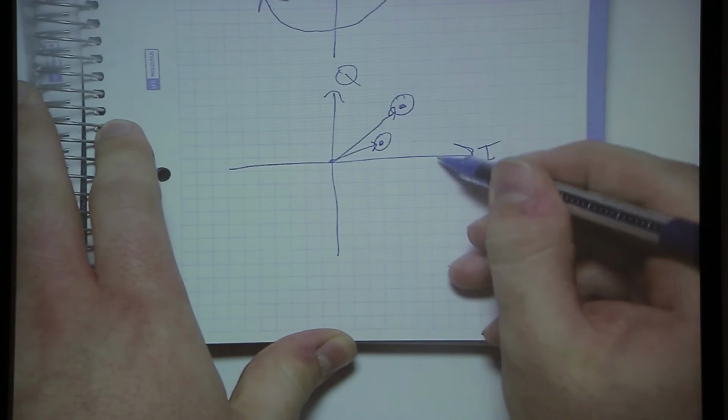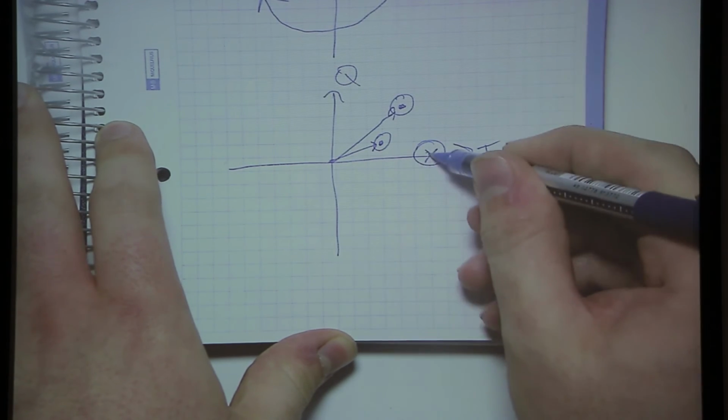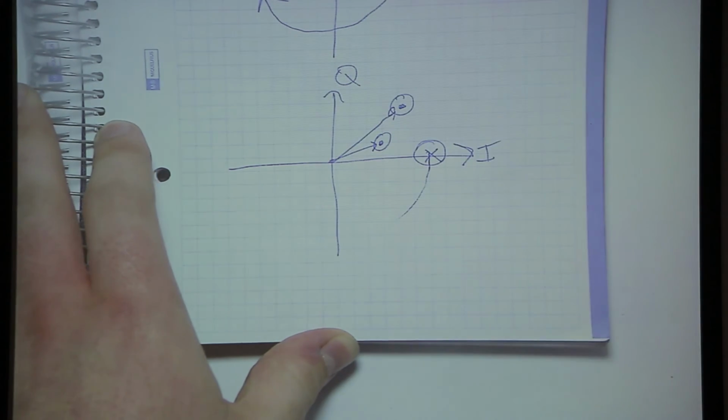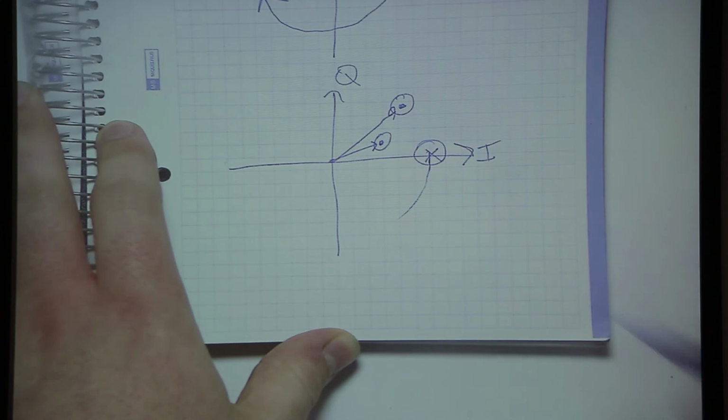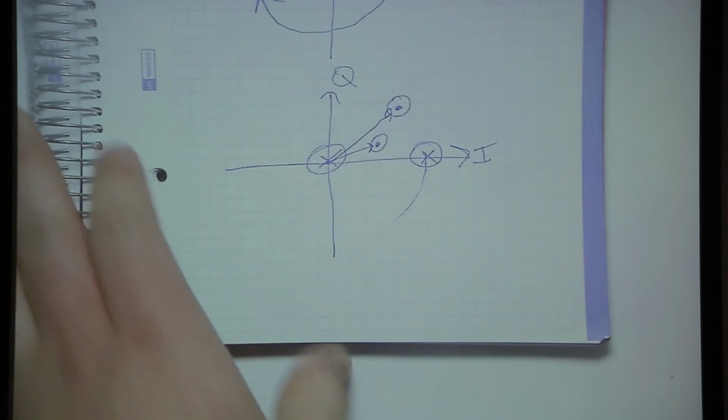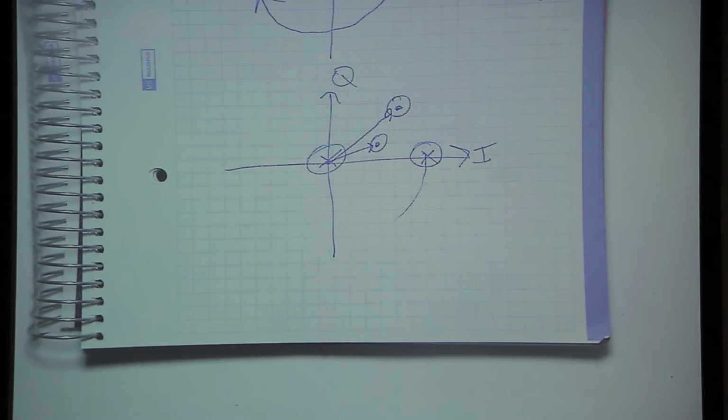If a radio is on, then the point can be over here somewhere, or really anywhere on this whole circle, because they all have the same amplitude. And if a radio is off, then it's in the middle, assuming it's at just the right frequency, say. And that means if you want to decode Morse, you just have to know whether the point is in the middle for 0 or close to the middle, and on the outside of a circle for keyed. And then I guess you have to do your timing stuff. But so Morse is fairly straightforward.